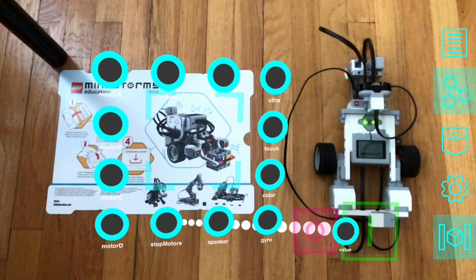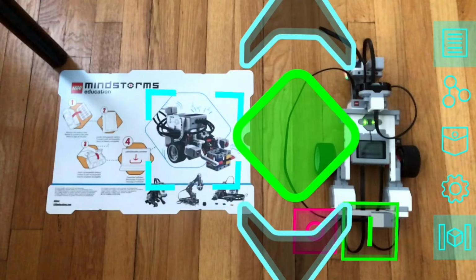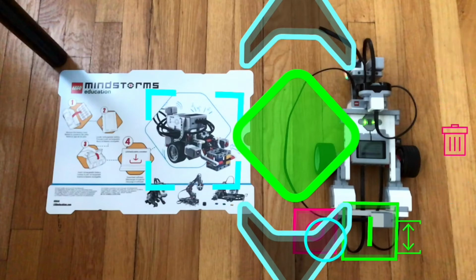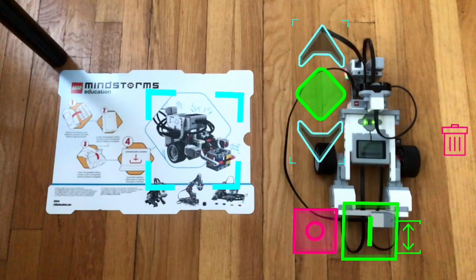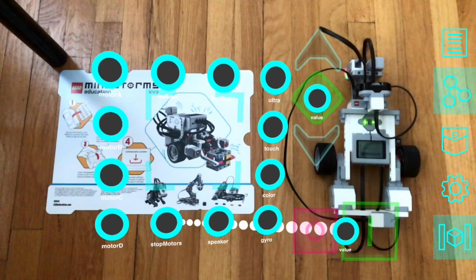And then next we're going to go into the pocket and drag in a slider. So this is going to connect to a bunch of different nodes. Our motor nodes can actually take values between 0 and 1, and they will scale them up by 100 to send to the EV3. So let's first connect our slider up to the two LEDs so that the lights will change as we change the speed of our motor, and we'll connect it to motor A.